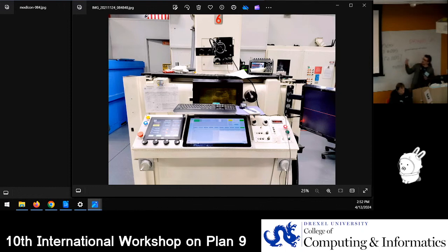I can have things like my PLCs, multiple in one cabinet, and I can boot them from one disk, and I can configure them all from NDB or the config directory, and write very small, simple code, and serve all these resources, such as field buses and all these I/O points, just as files. I could bind them all into a namespace specifically for a certain PLC control program, or I could distribute them, and have different small PLC processors all around the machine handling different tasks, and then they just supply small little files.